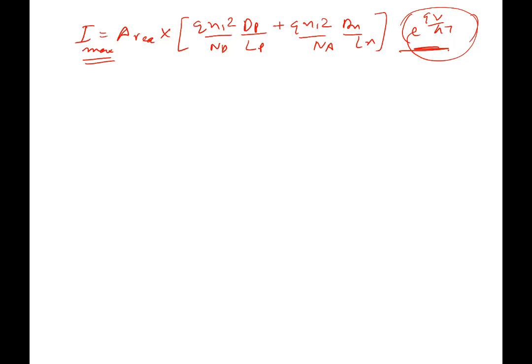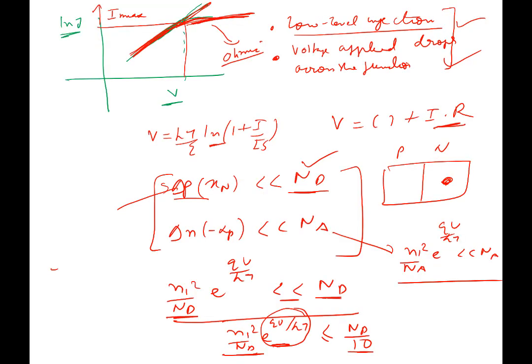The voltage drop across the PN junction becomes this thing here. So that's the upper limit of operation. You will say, operate it till this particular point here. Now this Nd by 10 is debatable. You can take Nd by 5. Some people may take even equal to Nd. The boundary is fuzzy, you could take it here and there. All right, so that determines the upper limit of operation.